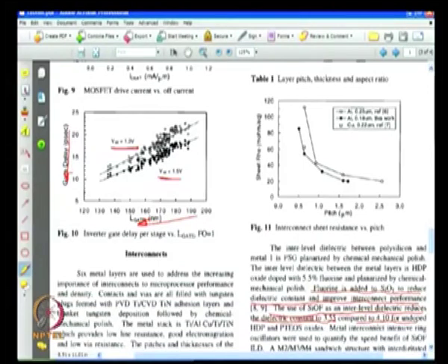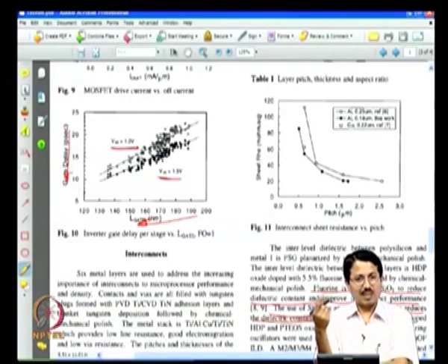You see, if oxide is thermally grown at, let us say, a high temperature of 1000 degrees centigrade, then its dielectric constant is more like 3.9. That is what we used earlier when we were talking of gate dielectric. 3.9 we round off to 4, but here we say 4.1 because this oxide is not thermally grown, it is a deposited oxide.